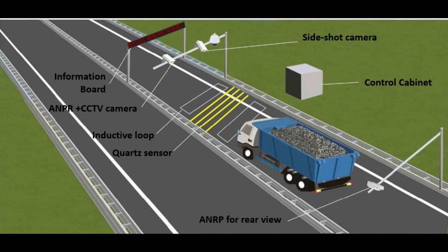When the vehicle tire contacts the load cell, the sensor begins to detect the wheel pressure, generates an electrical signal proportional to the pressure, and after the signal is amplified by the data matching terminal, the axle load information is calculated by the weighing controller. When the vehicle leaves the ground loop, the WIM controller calculates the number of axles, axle weights, and vehicle gross weight, and the weighing is completed. It sends this vehicle load data to the front-end manager equipment. The WIM controller can also detect both vehicle speed and vehicle type.